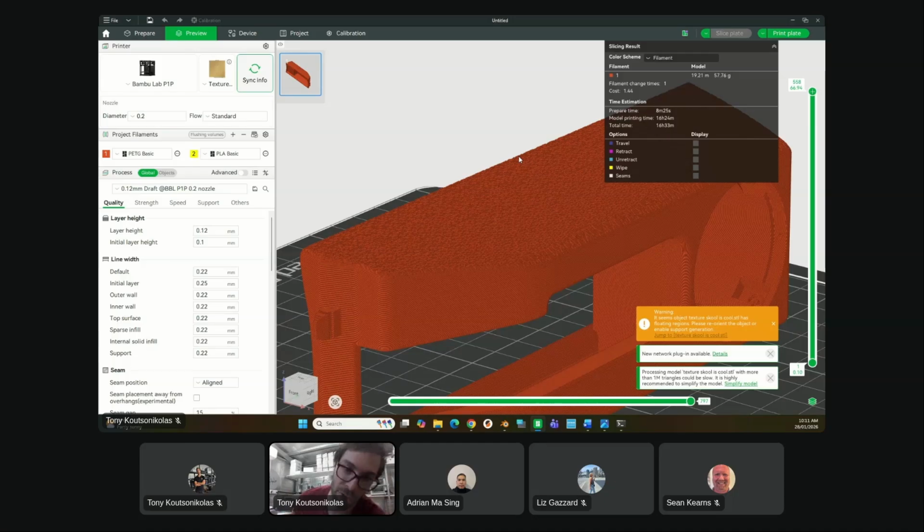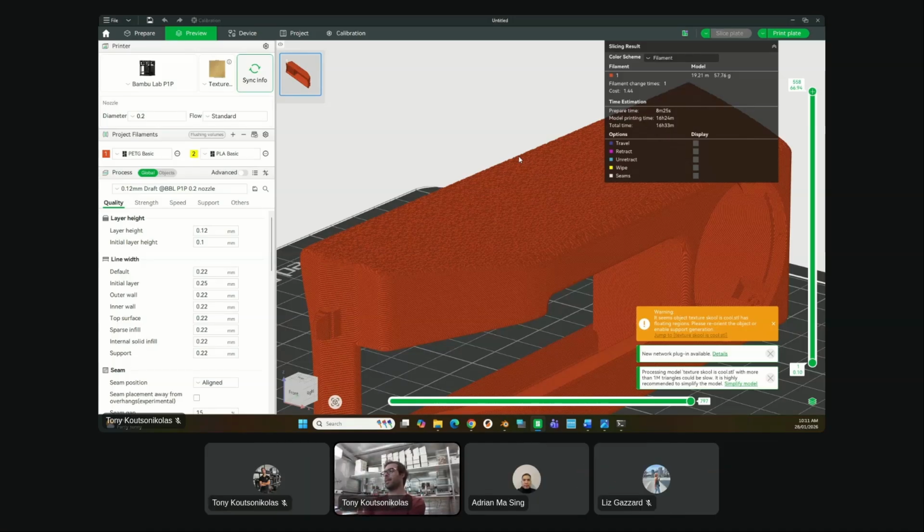If it's a curved surface, it might be hard. And the texture itself, you probably want to print so the Z plane is involved. Right, if it's flat, then it'll be smooth. So you'll need a few layers, and then you'll run into this same issue. Yeah, you're right. So if I was forced to make this part with the texture, I would make it with insertable plates or whatever for those sides.